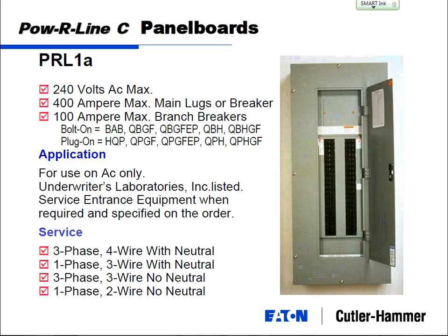Look right up here. You've got all your branch circuits. That's just like this panel here. What's missing up there? Circuit breakers. What kind of panel is that one? That's main lugs only. That's the difference. I can open and close this breaker. I've got no disconnect means on that.